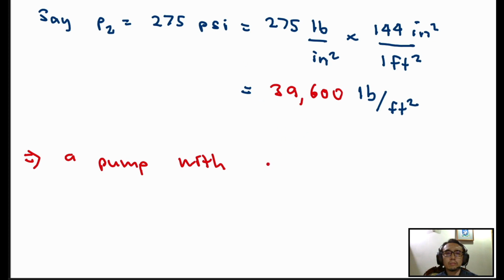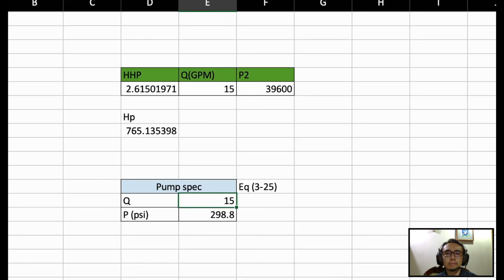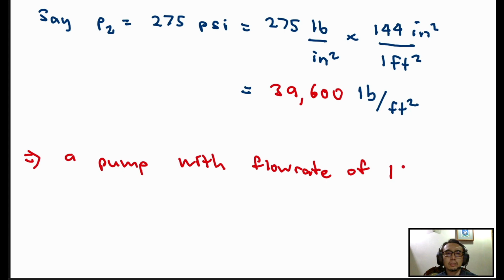So a pump with flow rate of 15 gallons per minute and 300 psi should work to solve the problem.